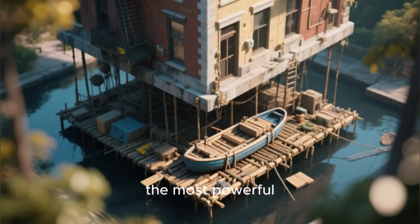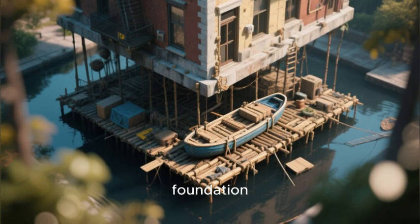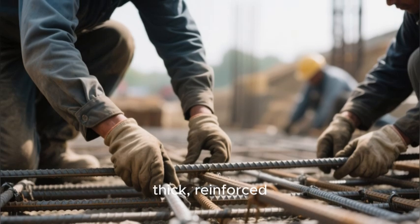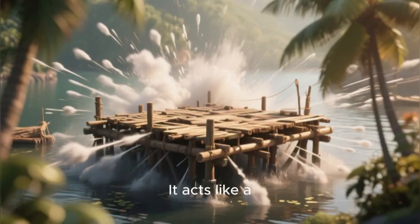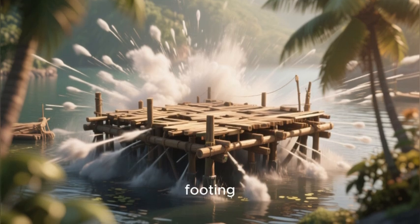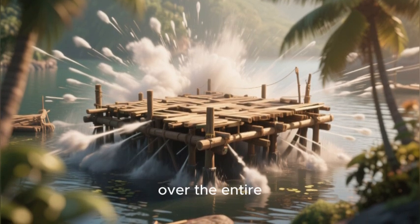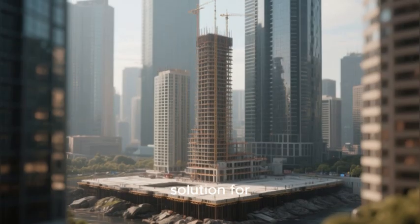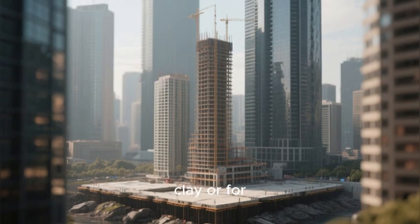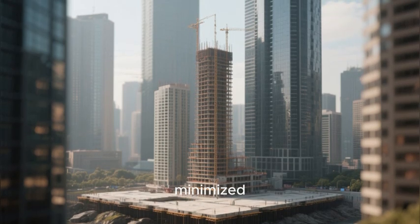Then you step up to the most powerful shallow foundation, the raft or mat foundation. This is a giant, thick, reinforced concrete slab that sits under the entire footprint of the building. It acts like a single, monolithic footing, distributing the load of every column and wall over the entire area. Like a raft floating on the soil, this is a common solution for high-rises on soft clay or for structures where differential settlement must be absolutely minimized.